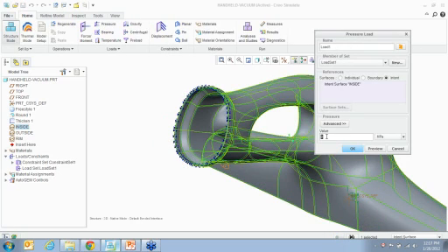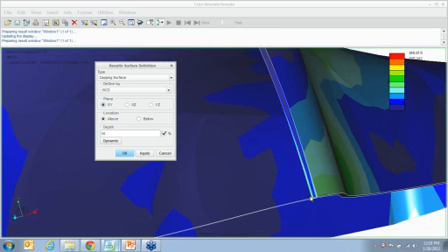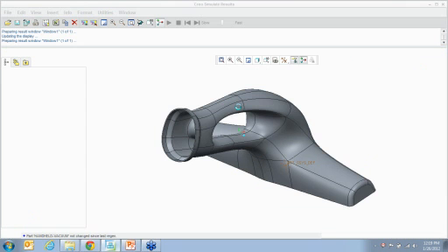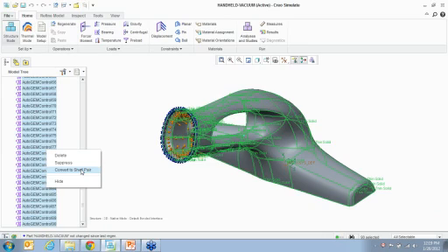We can go to deformed, shell element. In order to see solid elements, we could always avoid it. The enhancement within this is that once I create this mesh, I can always select a whole bunch of them from here and convert them into a shell pair, then create a shell element and run the analysis. This gives me a good comparison: I ran it as a shell element and got this result, I ran it as a solid element and got this result. Is there a difference? So you can do those kinds of things with it too.